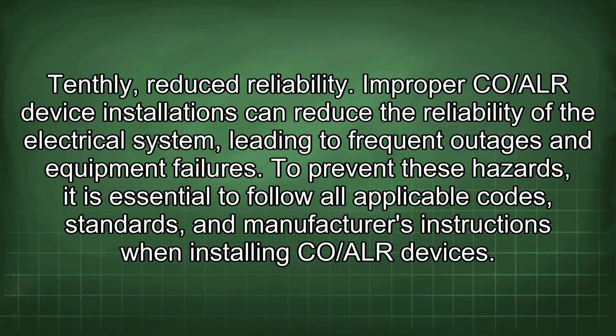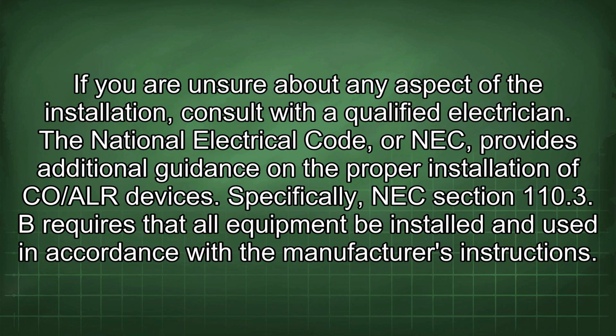To prevent these hazards, it is essential to follow all applicable codes, standards, and manufacturer's instructions when installing CO/ALR devices. If you are unsure about any aspect of the installation, consult with a qualified electrician. The National Electrical Code, or NEC, provides additional guidance on the proper installation of CO/ALR devices. Specifically, NEC Section 110.3(B) requires that all equipment be installed and used in accordance with the manufacturer's instructions.